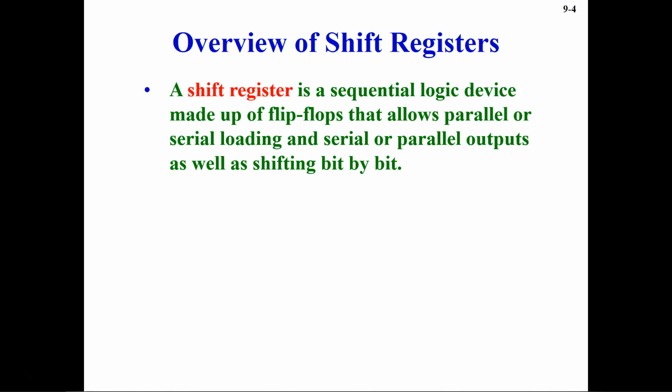These shift registers have flip-flops connected in cascade, and they share the same clock, in which the output of each flip-flop is connected to the input data of the next flip-flop in the chain, resulting in a circuit that shifts by one position, or you can say they shift bit by bit. Now let's see the different tasks which shift registers can do.